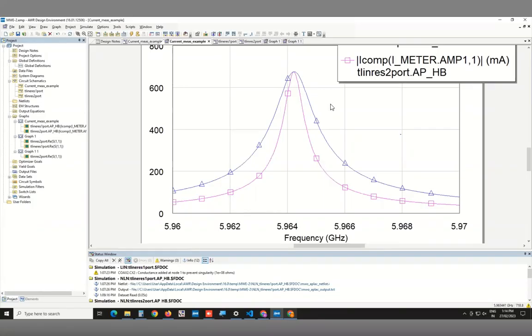But so you have a reference where the Q is about a factor of 2 smaller, and you get some current in the resonator. The other one has the situation that the power can actually leak out of the other side. So you would somehow expect that the current should have been lower, but it's not lower because the Q is higher. So the two are sort of compensating each other. The higher Q compensates the fact that the power is leaking out of the other case. But these are not really apples to apples comparisons. But that's how you would explain this.